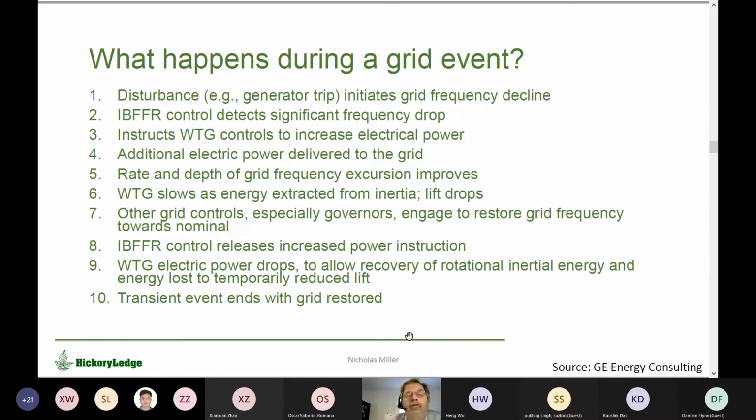You can't figure out frequency for control actions in a cycle or two with any confidence. People forget that. Researchers forget that. Do not forget that. In a real system, the waveforms are messy. Other things masquerade as frequency changes. So it takes time to respond, whereas the flux equations respond instantly. That's the difference between synchronous inertial response and controlled fast frequency response.